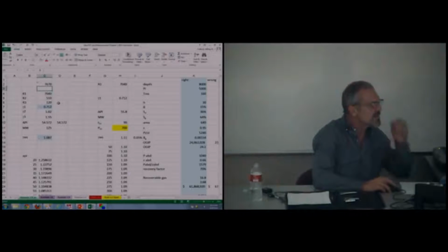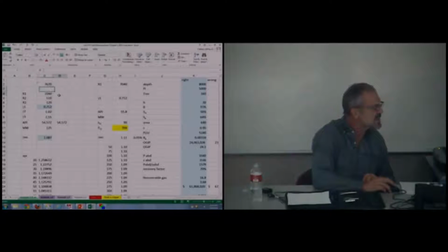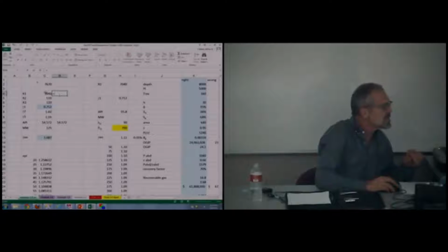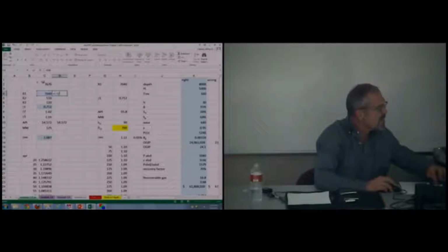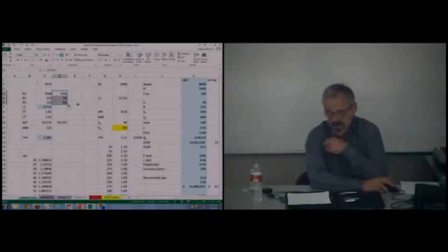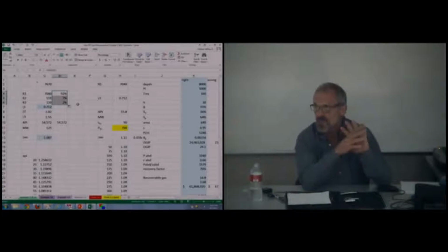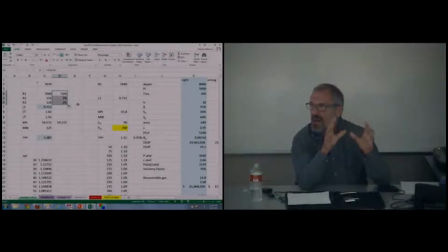We're selling, for every 7,670 MCF, most of it is coming off our primary separator. 92%. Only 7% is coming from the second stage separator, and only 2% of the gas based on volume. I'm still adding apples and oranges because these other gases have different gravities. So this is not a mole balance.